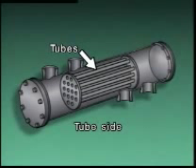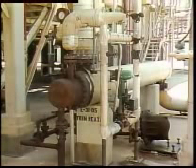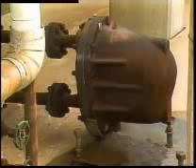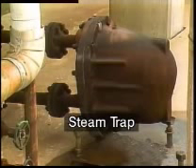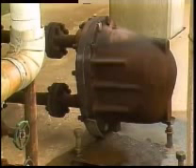The heads also contain a tube side inlet and outlet. On heat exchangers that use steam, an auxiliary device called a steam trap is often used. The steam trap drains water or condensate from the steam in the heat exchanger without letting the steam escape. Lost steam reduces the efficiency of the heat exchanger.